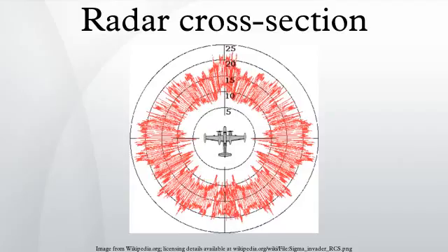Measurement. The size of a target's image on radar is measured by the radar cross-section or RCS, often represented by the symbol σ and expressed in square meters. This does not equal geometric area. A perfectly conducting sphere of projected cross-sectional area 1 m² will have an RCS of 1 m². Note that for radar wavelengths much less than the diameter of the sphere, RCS is independent of frequency.